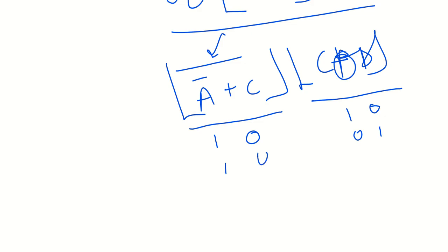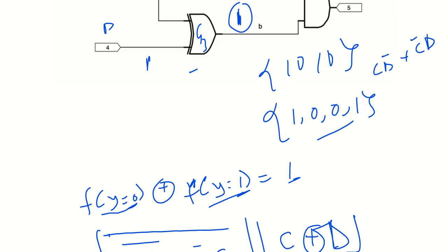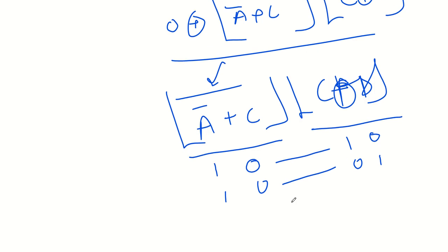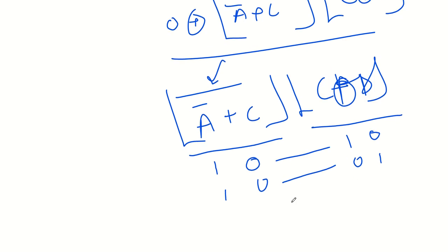So 1 0 again. So you realize that when you match them, it's either you have 1 0 1 0 or 1 0 0 1. Those were the two possible cases. And you realize that those were the two possible cases we had here for our path sensitization method. So either of them do give 1001. So I think it will depend on the one which does not bring any form of inconsistency during the backward propagation step. And so I think it's just the 1001.